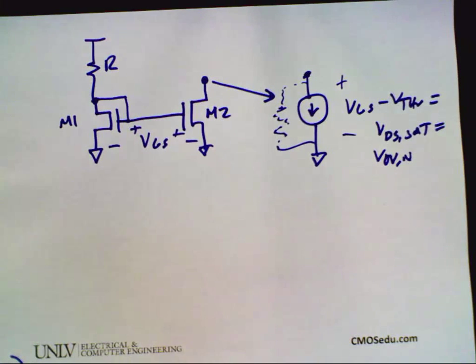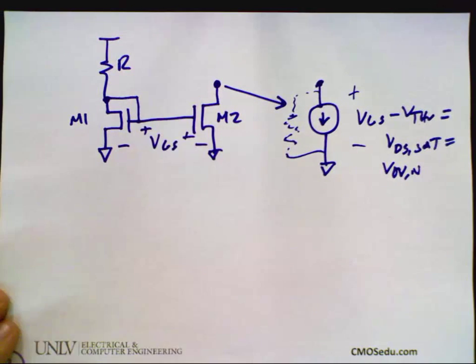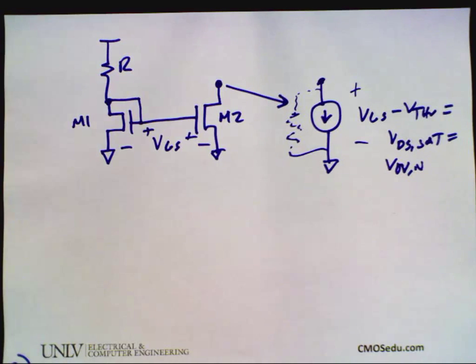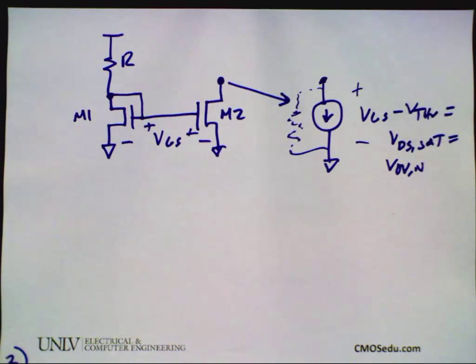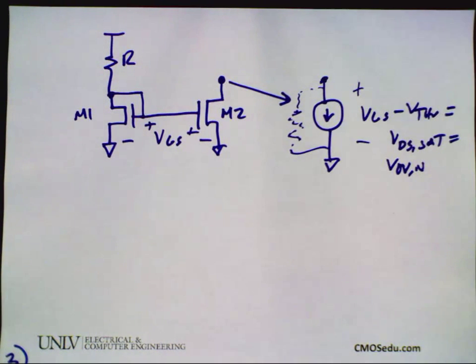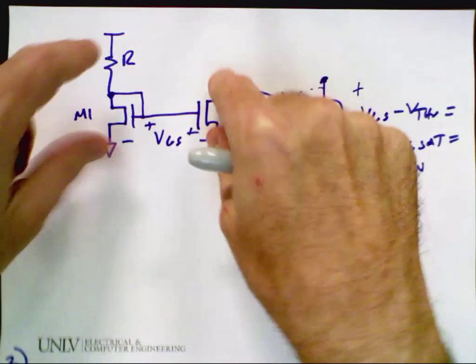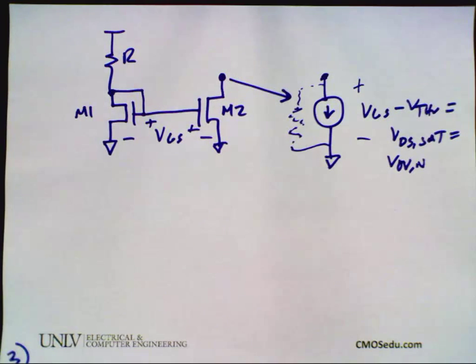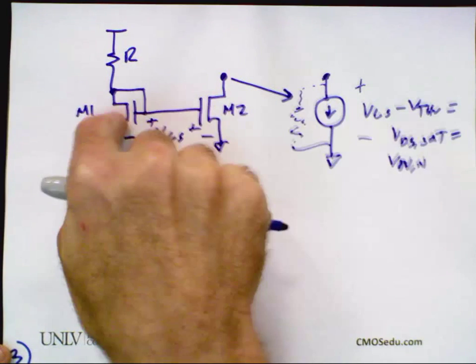It converts an analog current to drive the LEDs or whatever this is in the screen through a digital to analog conversion by weighted current sources. So you put the digital word in there, it sends the current to the display, and how much current or how little current changes the illumination in the red, green, and blue pixels. So let's say I wanted to have good resolution so I could zoom in on the pixels and see the difference between, you know, the edge of a star and a dark sky or something like that. What would I do in order to have good matching?